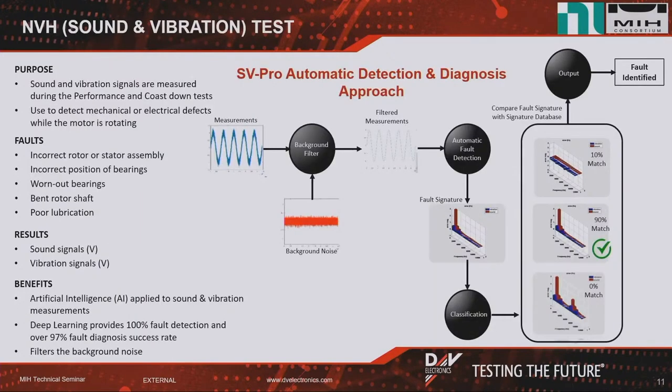So having done these tests, one of the capabilities that we offer is a noise and vibration, or sound and vibration test, actually, perhaps a better term, to provide another view of looking at the health of the motor. Now, this can be run without need of an anechoic or semi-anechoic chamber, and gives a good qualitative indicator in case of potentially any faulted conditions that might exist.